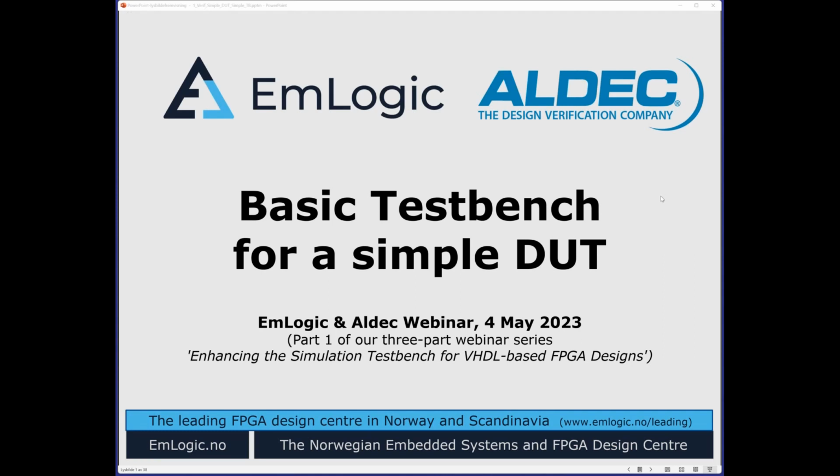We will also discuss the elements of a basic test bench infrastructure, show you examples of how to create self-checking test benches with verbosity and alert control, and introduce the use of basic bus functional models, BFMs, to speed up verification and debugging.